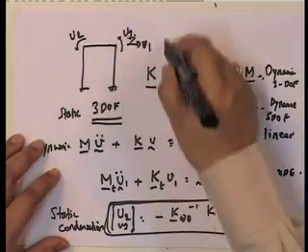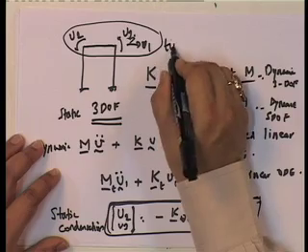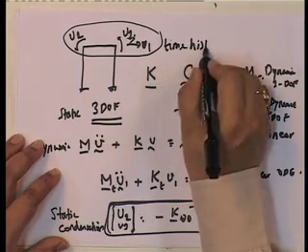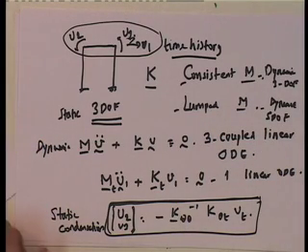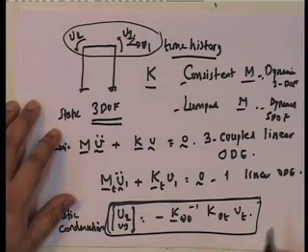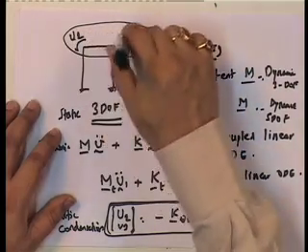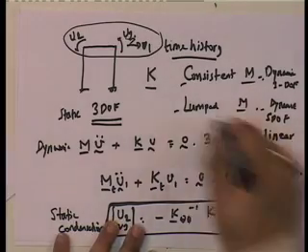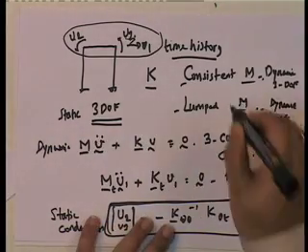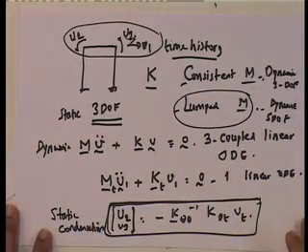So, you have to find out these 3. You have to find out the time history of all of these to be able to get any response. The only thing that happens here is that you only dynamically solve for this, and these two then become just a pseudostatic relationship rather than a dynamic relationship. So, that is why the lumped mass formulation is a preferred formulation to the consistent mass formulation.